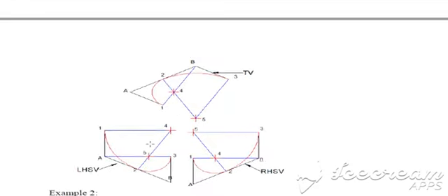Let's see it again in a right hand side view. With 4 as a center, distance till the perpendicular as radius, mark an arc. With this point as a center, distance till the perpendicular point as radius, draw an arc. In this way you can draw the semicircle.